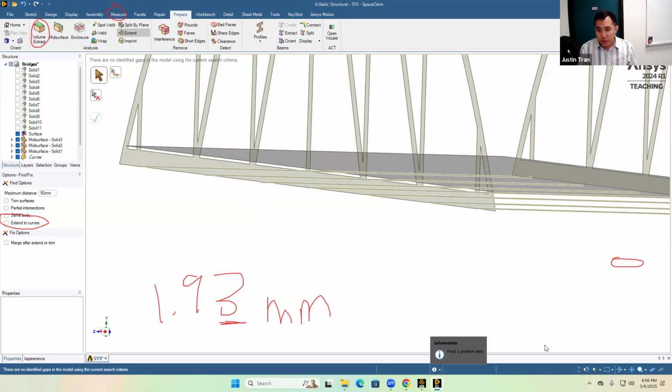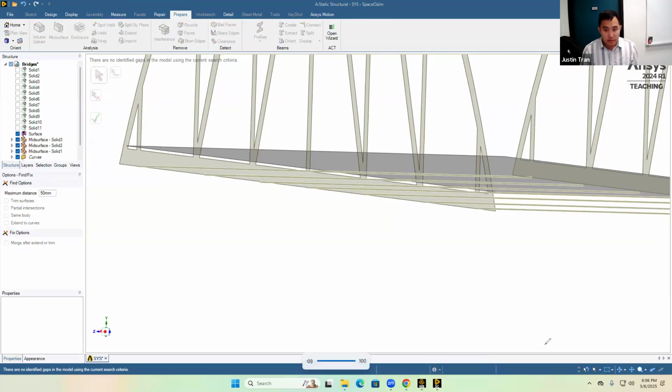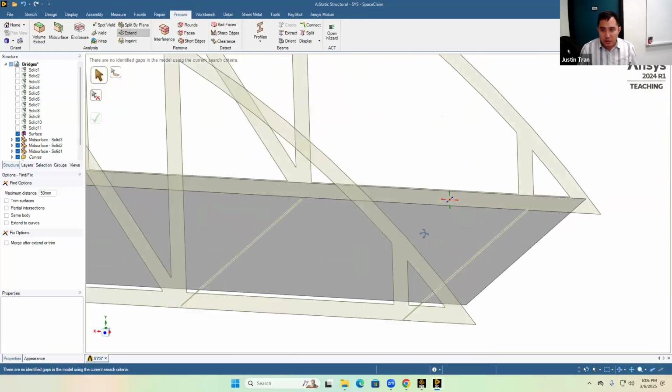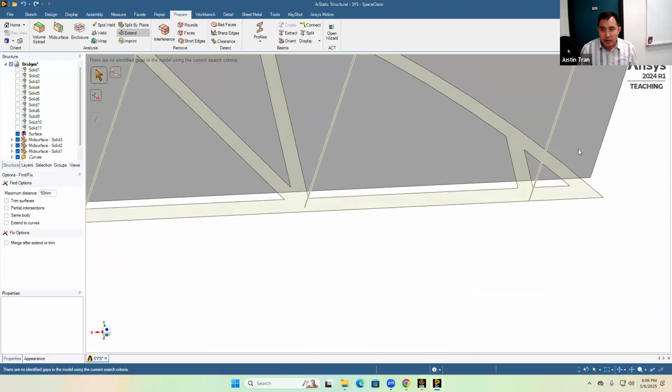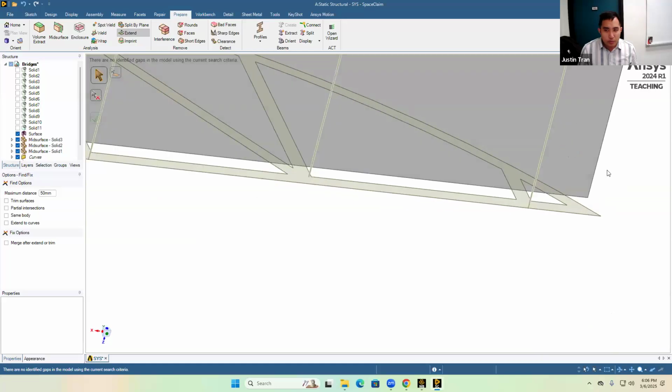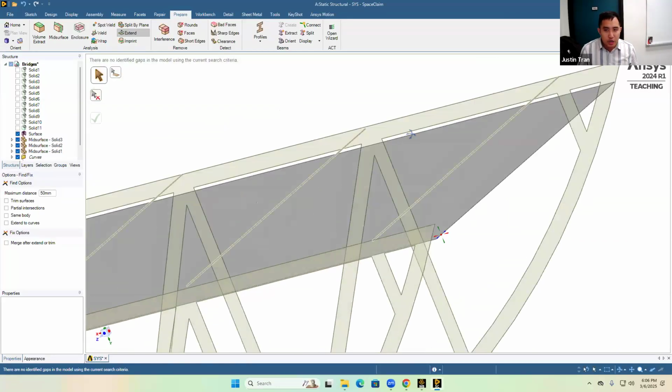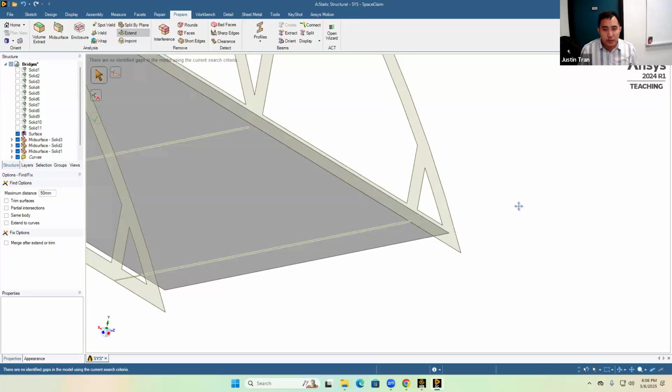You guys doing okay on Zoom? Any questions? Yeah, actually, someone had that same issue too. What's happening is that for some reason SpaceClaim is thinking that whenever you create a beam, it looks for a section of geometry with a consistent shape.